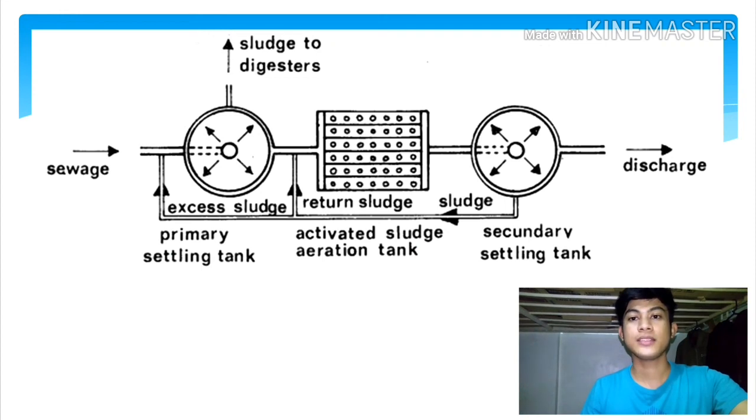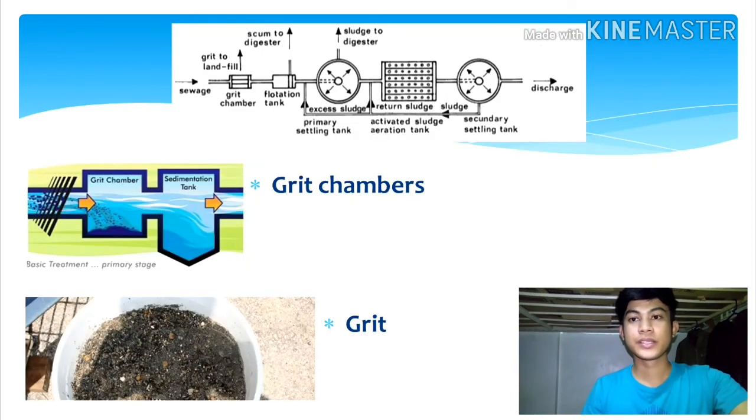Next, the activated sludge process is a biological wastewater treatment operation. This means that treatment occurs through many different microorganisms using pollutants as a food source. Grit chambers are long, narrow tanks that are designed to slow down the flow so the solids such as sand, coffee grounds, and eggshells will settle out of the water. Grit causes excessive wear and tear on the pump and other plant equipment.